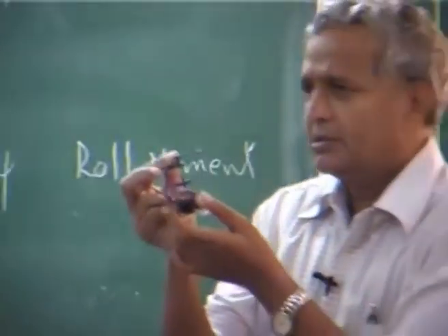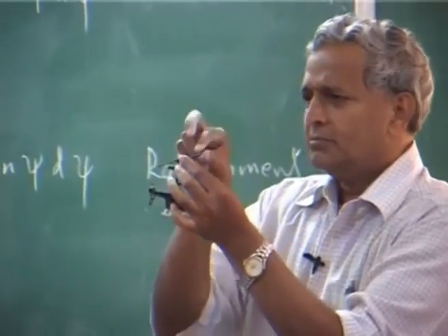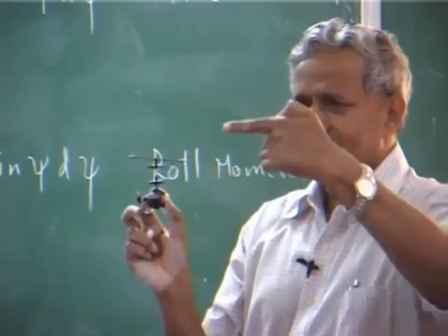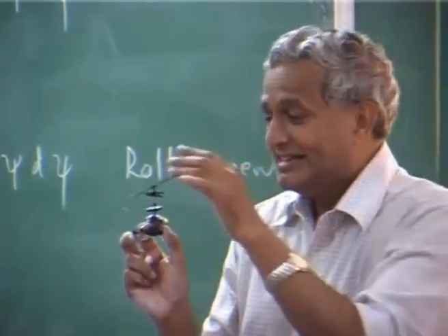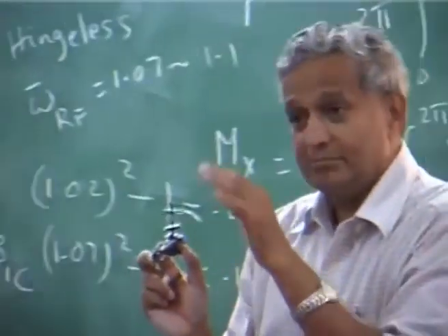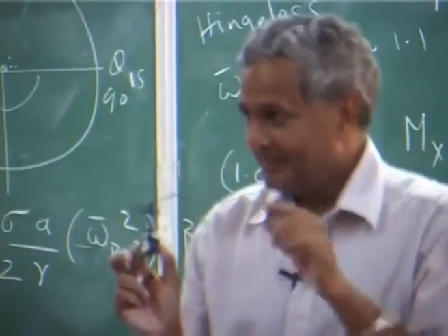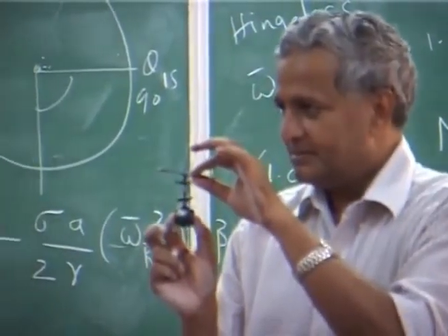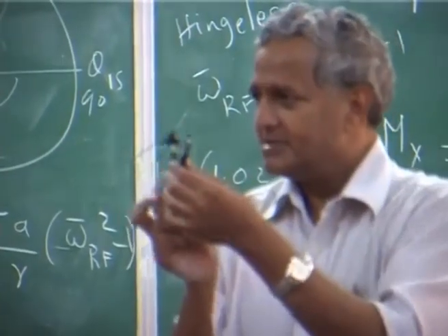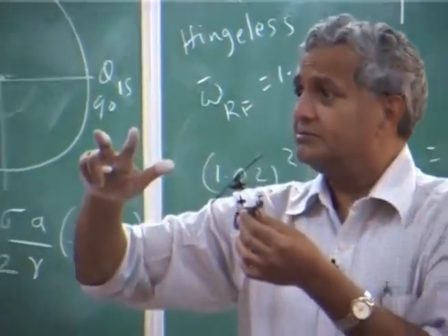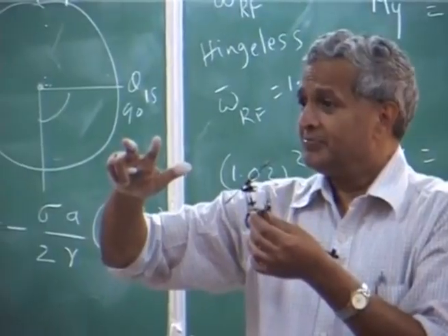This does not have any aerodynamics, only two masses, just like a stick which is spinning. Okay. This is called the stabilizer bar. Now you see this has an inertia, it keeps rotating. So even if I tilt my shaft, it takes some time for it to come to the other position.